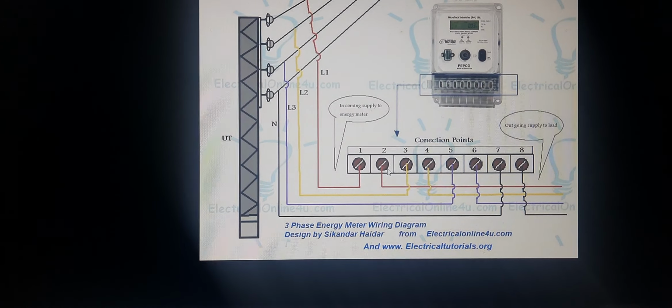I'll show you. It will be like this. It will come out separately like this. So this is the idea actually. So this R phase voltage will come out separately in the case of LTCT metering, where we are not using any PT, but we are using only CT in LTCT metering. So this is to understand things actually.